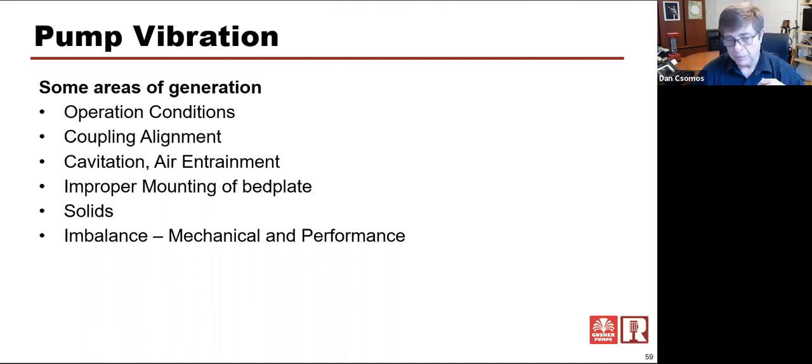Well, this pump had pumped this 2-inch by 18-inch long angle iron several times through the pump, and it got caught going to the discharge valve, the check valve and the throttle valve on the discharge side of the pump, and couldn't make it past there. Well, it would sit there and rattle, and that's what was causing all this vibration. When you shut off the pump, the thing would drop back down into the tank generally, and we wouldn't be able to see it.